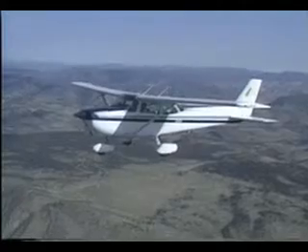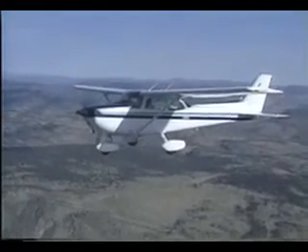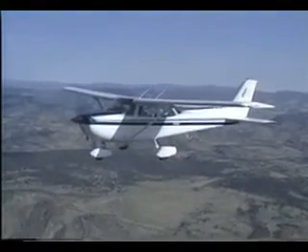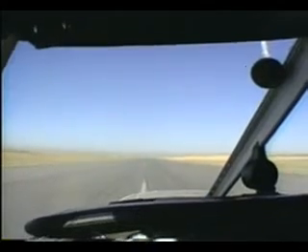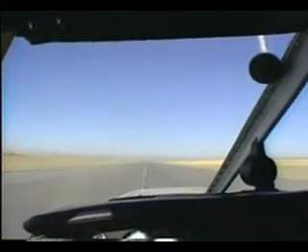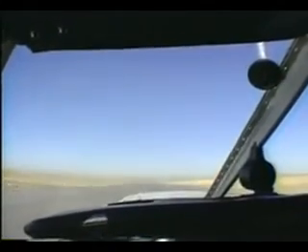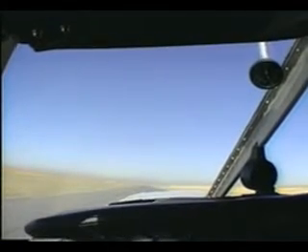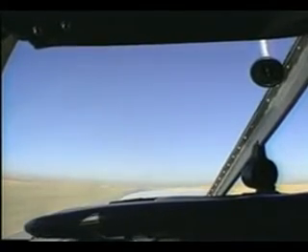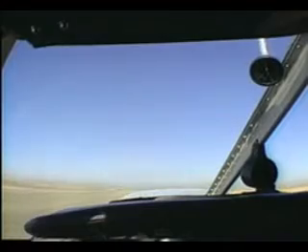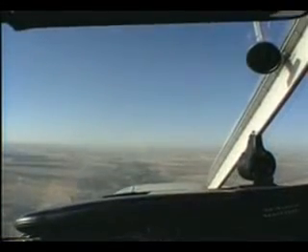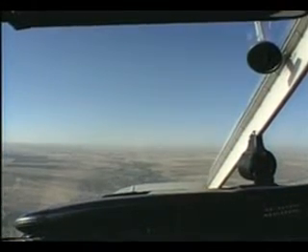A propeller with a low blade angle is capable of producing more RPMs and is best suited for takeoffs and climbs. A blade with a high angle, however, is more efficient for cruise flight. Most light training airplanes use a fixed-pitch propeller with an overall blade angle somewhere between a true climb propeller and one designed just for cruise. This provides relatively efficient thrust throughout the airplane's operating range.